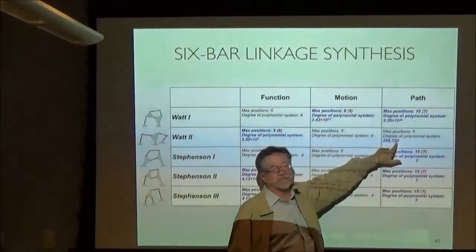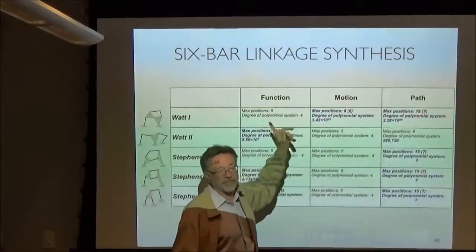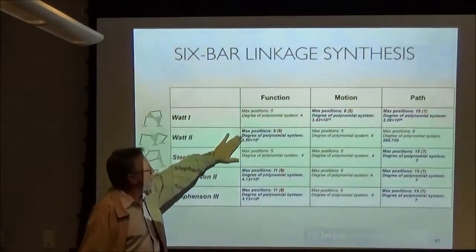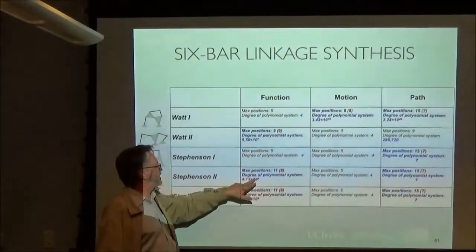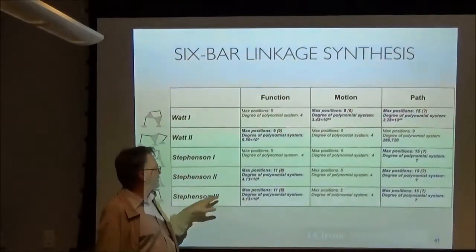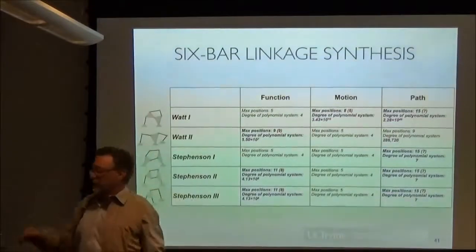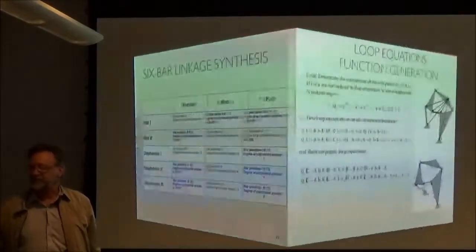This again reduces to the same problem as the 4-bar linkage. This is the one we've been able to do. We've been able to do 8 positions for the Stevenson 2 and 8 positions for the Stevenson 3 and 6 positions for the Watt 1. And I'm going to show you those results.